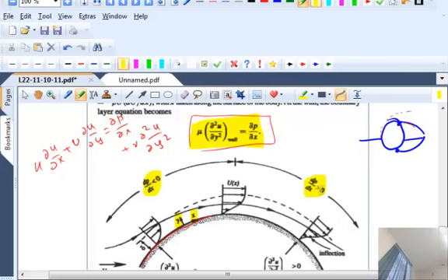If there is friction, there has to be a pressure decrease. Right? So the pressure gradient is negative, but once the separation occurs, the pressure gradient actually becomes positive. And that means the second derivative of the velocity field must be 0 at the point where the pressure gradient is exactly 0. So it develops an inflection point. And that's how you can detect where the separation point is.